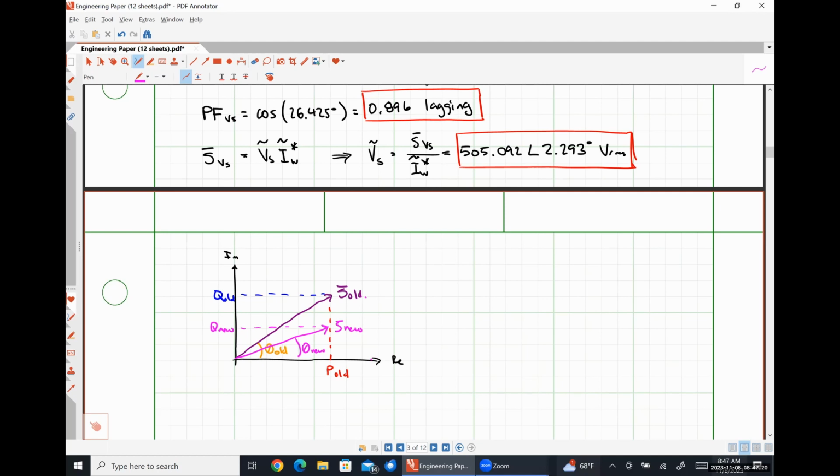Our angle is smaller, which means our power factor has been corrected. Our average power has remained constant, which means we're not incurring any repetitive costs by doing this because we're not running up our bill month by month by month. So whatever we do to decrease our Q is really just a one-time cost, hopefully, right? So this is the way that power factor is traditionally corrected in an industrial system.